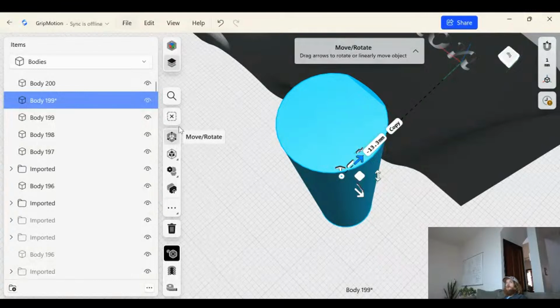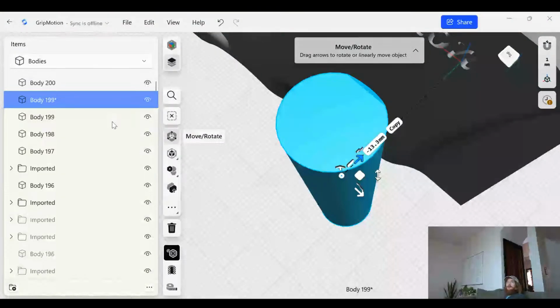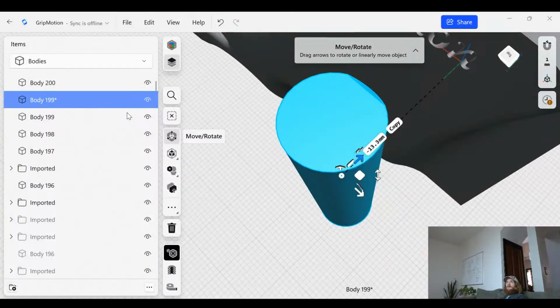So what you're going to want to do is import to current project. So we're going up to File, Import to current project, and I'm just going to, what do I got here? I could go into... I don't have any STLs.